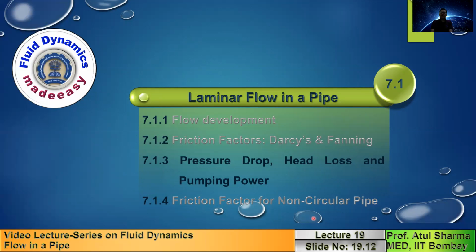In the previous topic on Bernoulli's equation, I had mentioned that pressure can be expressed in different types of quantities. So we also express pressure in terms of head by dividing by rho g. The pressure drop that occurs due to the viscous resistance in flow in a pipe, if you divide by rho into g, gives a term which is called head loss.